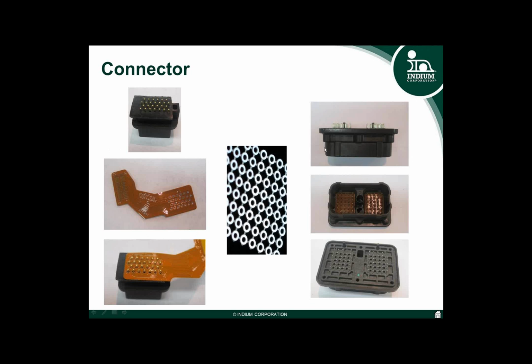And again, on the right-hand side, you can see a slightly different way of manufacturing an automotive connector. Here you can see there's an embedded connector. Then there probably would be some filling of a dielectric gel as an insulative measure for the connector. Maybe it's used in harsh environments to meet its mission profile. And then you can see the lid placed on the top side of there for a mechanical reinforcement.